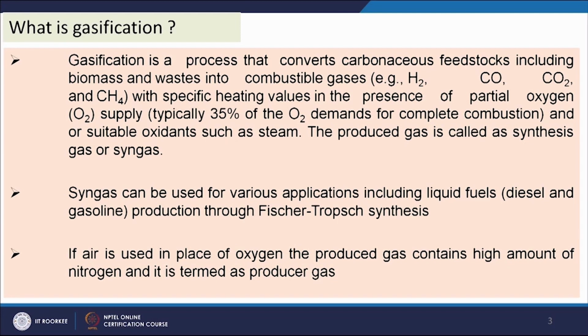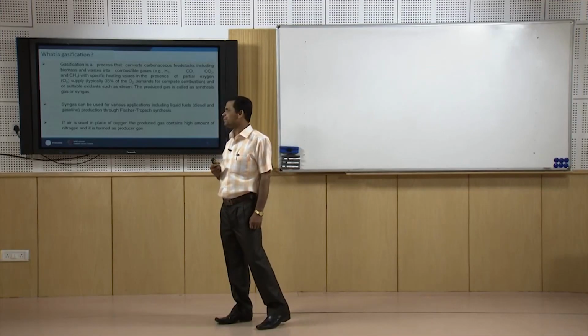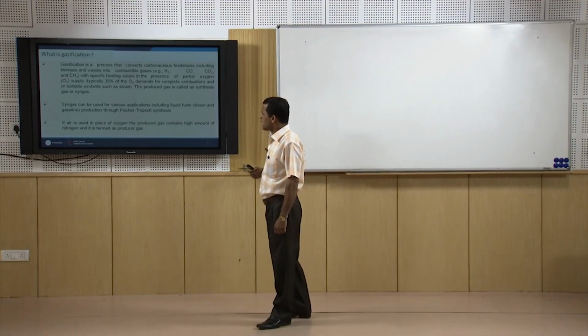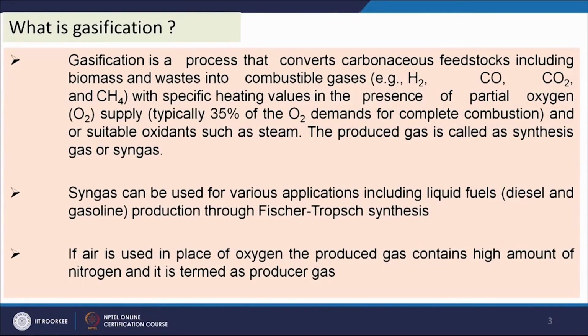The produced gas is called synthesis gas or syngas. But if air is used in place of oxygen, then a large amount of nitrogen is also present in the produced gas and the gas is named producer gas. Syngas can be used for various applications including liquid fuel synthesis through Fischer-Tropsch synthesis routes.